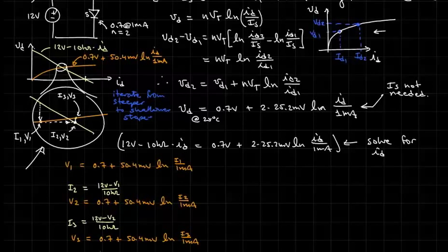I've indicated that on the IV curve here, and have labeled IV pairs, and so we will use the diode curve to calculate voltages from currents, and then we will use the load line to calculate currents from voltages. And we begin with I1, an initial guess.